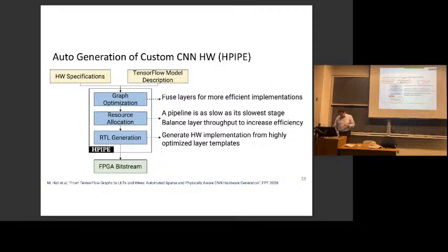So this architecture is called layer pipelined. We've got all the layers computing at once. Each of them is computing on a little bit of the input image, right? So we can't compute in parallel all of the data for the first layer of the CNN or the second. It would be too much hardware. So instead, with these processing elements that I talked about, if I go back here, this is working on a small part of the input image, and it's gradually scanning across it and producing output. And this PE is similarly working on a small part of the output that will come from the first layer.